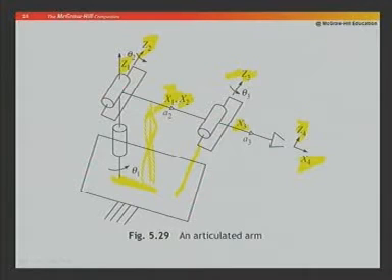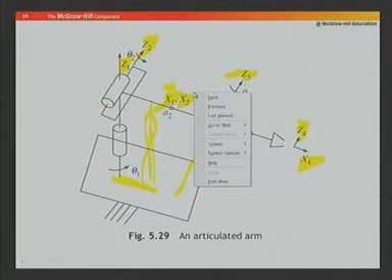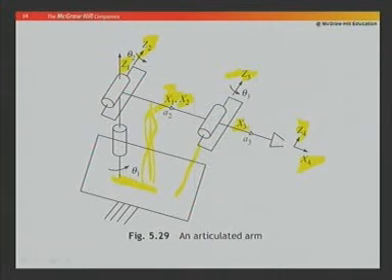Now, you refer to the values which you have noted down. Bi, that means B1. So, B1 is the perpendicular distance from Z1 to Z2. So, do we see any distance between Z1 and Z2? Here the Z1 and Z2 are intersecting. So, they are not separated by any positive or negative value. So, they are 0. So, B1, in the table you have noted down, comes out to be 0.